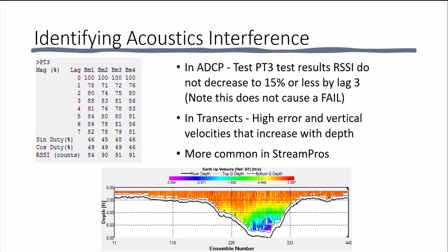Normally, as the signal strength drops below that threshold, the correlation will decrease, and when it drops low enough, the data will be flagged bad, which is expected and desired behavior. The negative impact of this type of interference is that the range will be reduced and data is more likely to be marked invalid. The second form the interference can take is that of elevated correlation.